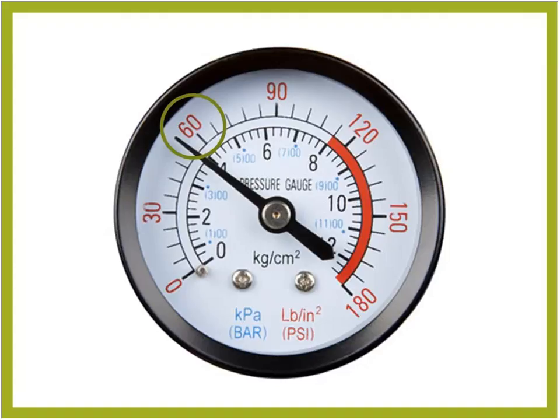And then, of course, lower water pressure, which you typically find in more rural areas, is going to lead to even lower flow, and then make the lower flow devices you install not work as well. So it's important to hit around 60 psi. There are water pressure regulators that you can help your clients get if the tests aren't coming out in that 60 range.